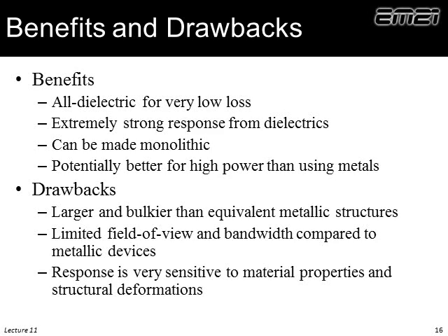That's very unique. We can make things that are monolithic. Later in this set of slides, we'll step through the design of a completely monolithic filter. It's a slab of dielectric. We cut some grooves in it, and it's a guided mode resonance filter. So it only has one material. That makes it very robust to vibration, to shock, to thermal cycling. And if we have to combine multiple materials, they can delaminate. Maybe one will be sensitive to some kind of chemical that might be in the vicinity. So we can make very robust devices out of guided mode resonance. I think also because they're dielectric, they're potentially better for very high power beams, better than metals, where metals can arc and the loss can produce heat and stuff like that.